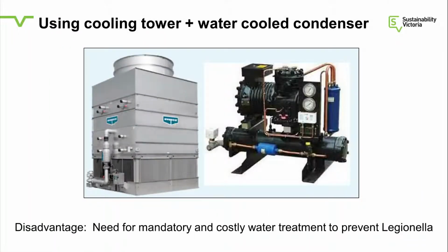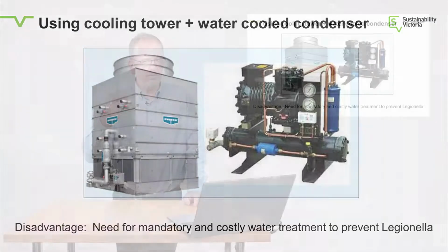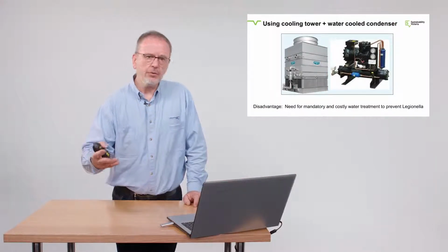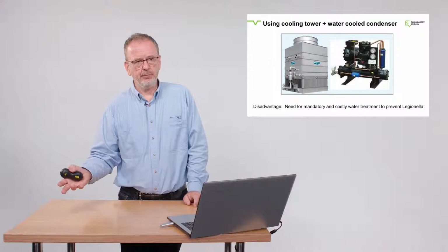How do we do that? The cooling tower is the obvious solution, and sometimes this works. I often see large buildings where there is a cooling tower already for the air conditioning, and then they put an air-cooled condensing unit in. It's kind of sad because you could have just tapped into the cooling water and had 30-40% energy reduction. So sometimes one just has to look at what's available. If there already is water cooling available, use it. Don't put air cooling in.